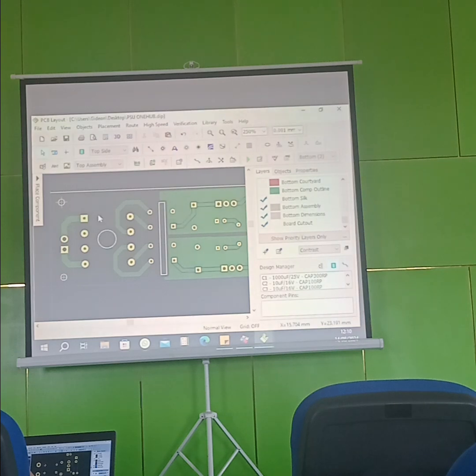So a drill file will give the position X, Y, Z, and the diameter of the hole. The diameter of the hole is what the machine will use to request drilling bits. It will tell them to insert a drilling bit of a given size in mm. When it's finished drilling that hole, it will stop and request another drilling bit for the next hole to be drilled. So those are the two pieces of information you send to your PCB fabricator.